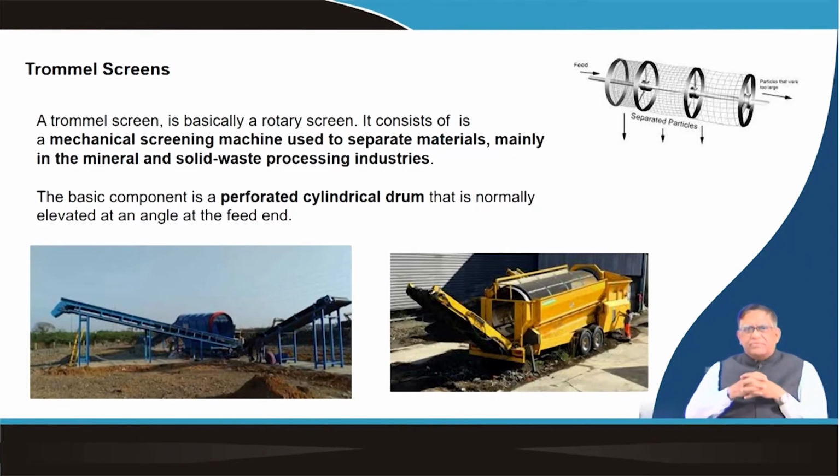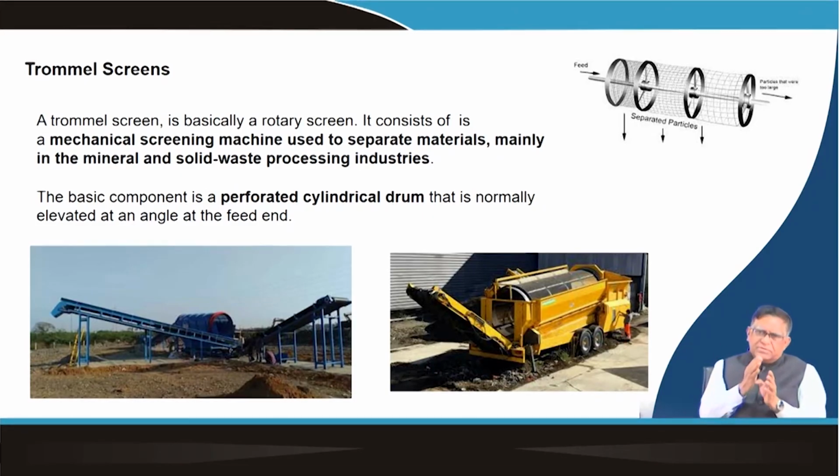Now, you may be seeing some of the screening operations of different types of bulk material, say in our municipality waste. From there, when you want to do that, that is also a screen, which is a trommel screen. We also use it in mineral processing, sometimes separating some of the coal particles. There also we have a trommel type, in which the whole crushed coal will be given, the trommel will be rotated and the finer, that is small size coal, will be taken out.